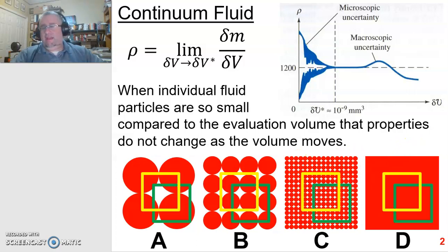And again, all the fluids that we're going to deal with in this class are continuum fluids, but it's important to know that there is this situation out there, especially if you start dealing with MEMS fluids or nanofluids, where the continuum fluid model breaks down and you cannot use just the standard equations. The first thing to go is probably the need to deal with surface tension, right? Surface tension effects happen at kind of a millimeter scale, so you have to start worrying about those when you have fluids that are about a millimeter in scale. And then after that, the no slip condition goes away, and that's fluids that are sort of on the micron scale that you have to worry about.